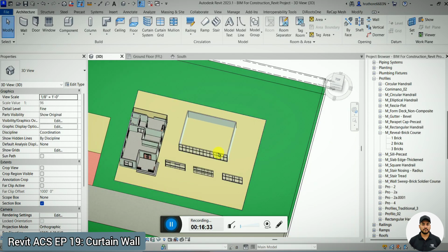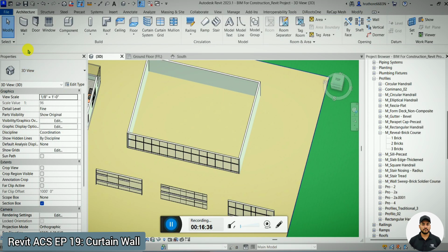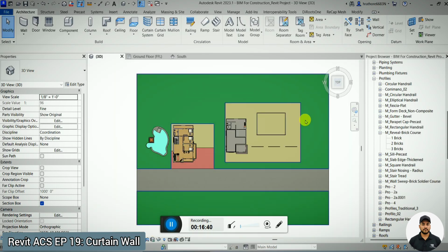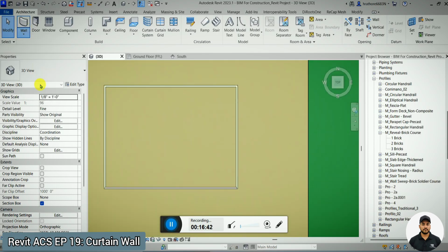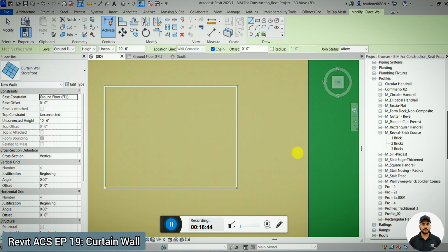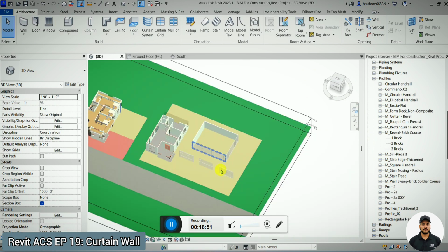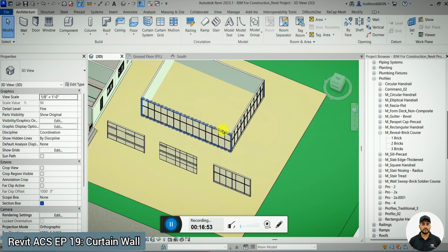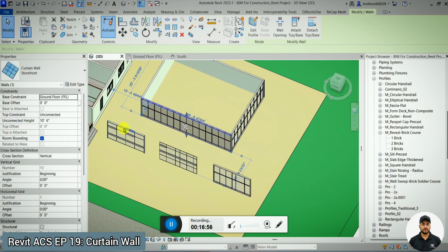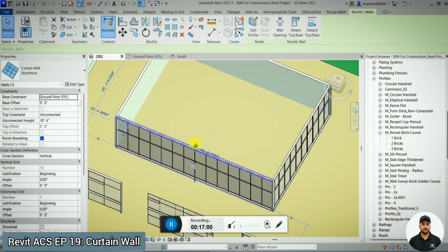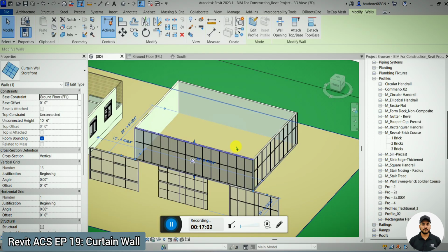Okay, this wall we need also here. Go to wall again, wall architecture, glass storefront. Here also I'm creating the same. Okay, so like this you can create a curtain wall with mullions or a curtain wall with glass only, whatever the first, second, third options, you can create such kind of curtain wall and mullions for any of your existing walls if you want to create in your existing wall.